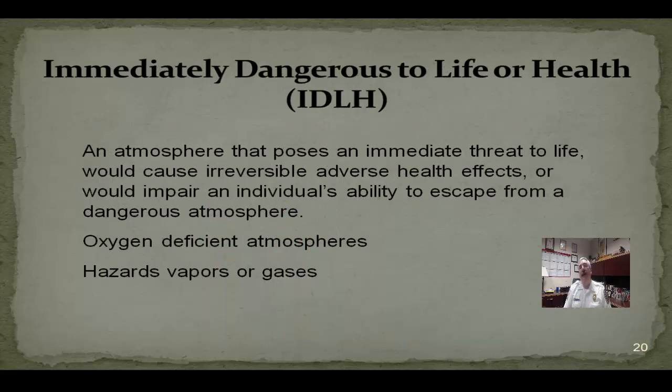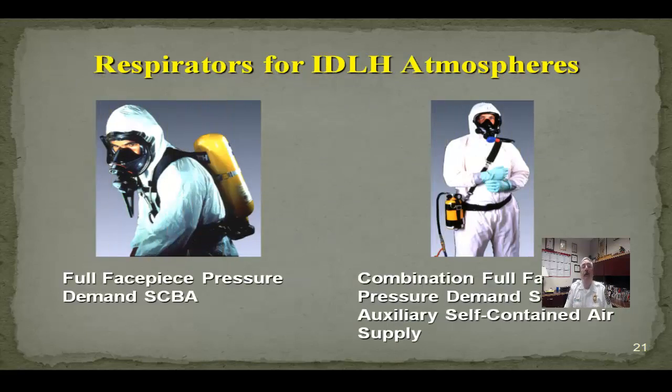Remember, at any time that you encounter an environment where you can't determine what the particulates are, or whether the amount of oxygen that's in the air has vapors or gases, you should automatically assume that that atmosphere is IDLH, immediately dangerous to life and health. And with that, there's only one type of respirator that's appropriate, and that's an atmosphere supplying respirator. Again, the full-face SCBA, self-contained breathing apparatus, or a full-face regulator with an SAR, supplied air system.